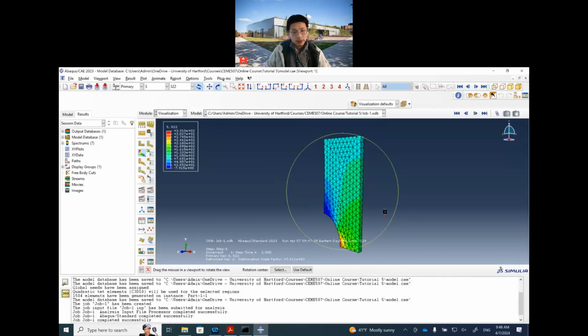So that's how we, I would say, create the model using 3D elements. Creating is very straightforward. The only issue is anytime you use 3D elements, you had better consider reducing the overall size of this problem, such as considering the symmetries and having a smaller number of loads and elements, so that you can run it in a much shorter time.